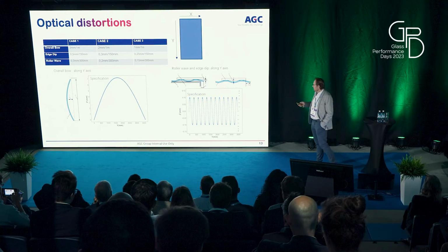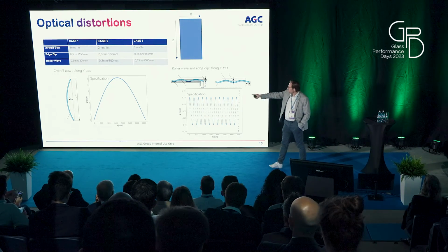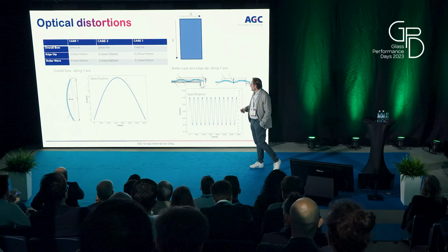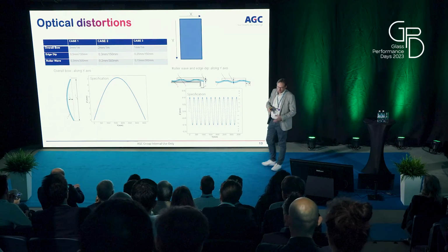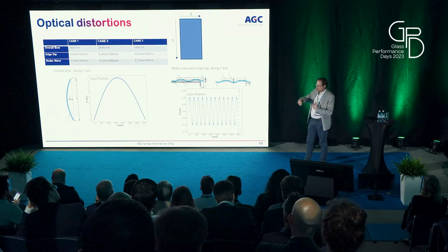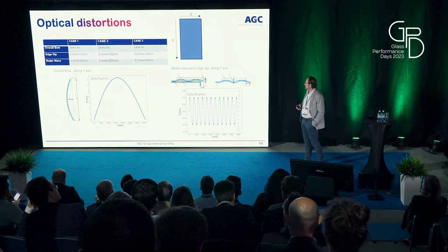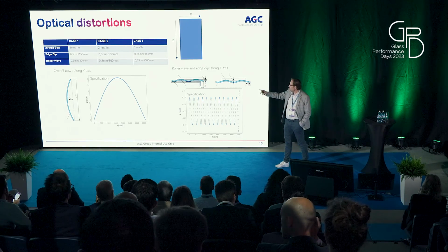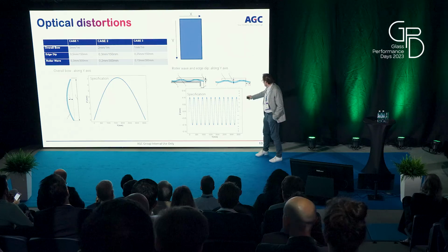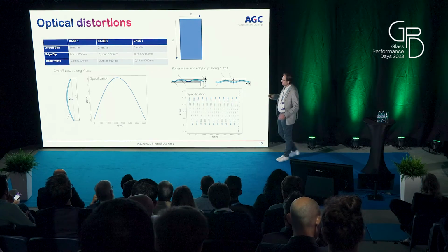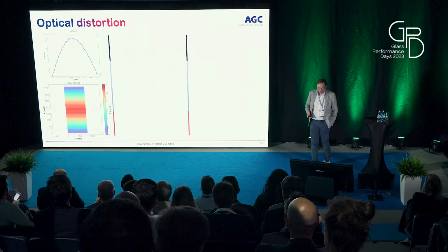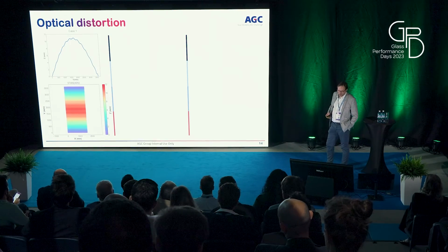Then we have combined all these tolerances, as you can see on the left image here below. The overall bow is over the height, because we assumed that the tempering was taking place with the short edge first, and then the long edge was coming, so the trailing and the leading edge, which means we go over the 3.6 meters, and the roller waves are parallel to the width, which means parallel to the 1.6 meter edge. This we have then combined in a distortion image, let's say.